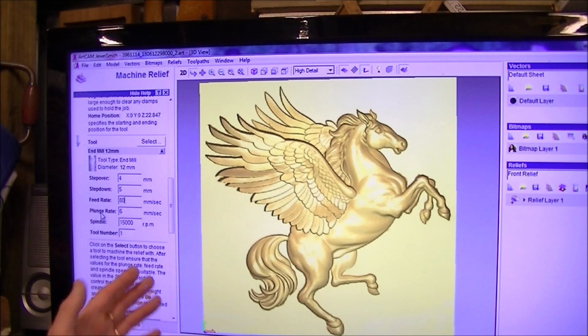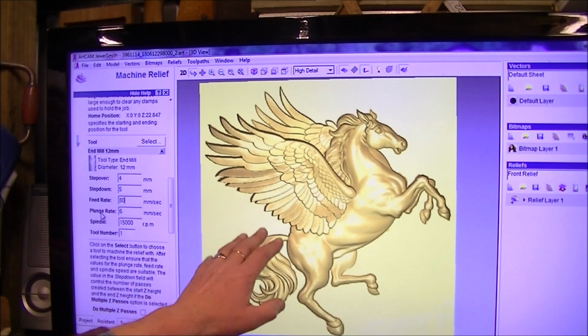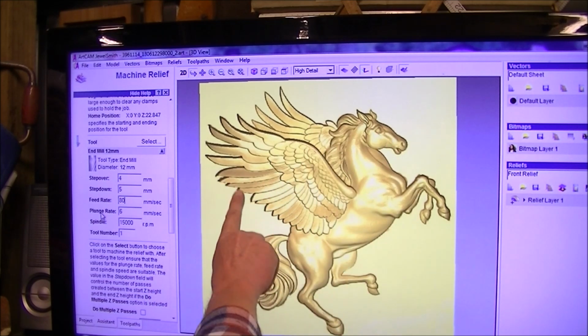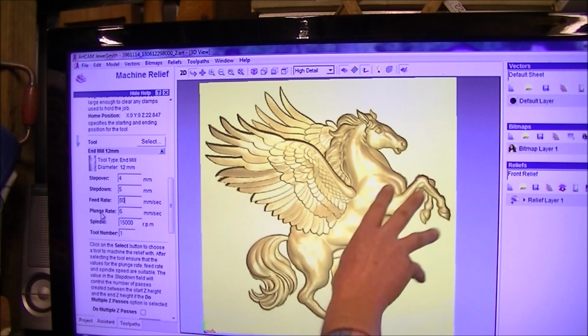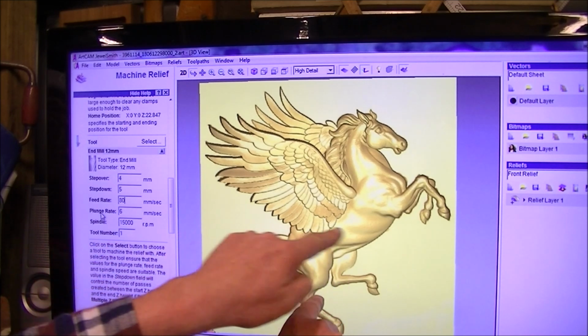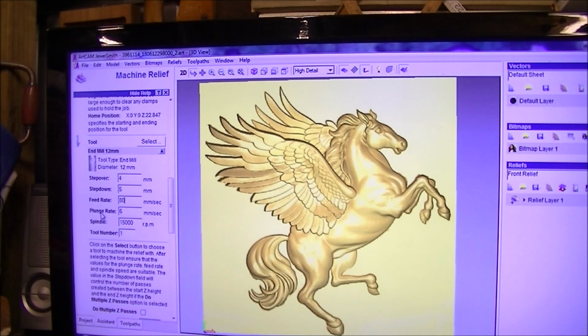What it's saying is it is the maximum feed rate possible in flat areas. When it's going over a corrugation area, the actual 3D relief, it does slow up, because you have to take into consideration the Z-axis has to pull up and push down, as well as the feed going in the X direction. So the machine takes a little bit of time to compose itself to do that. So this is maximum feed rate.